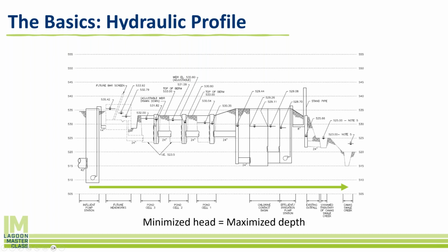Doing this math is extremely important all the way across because A, we need to make sure that if we're trying to move water to the next phase, the water level at that point is lower than the water level here. If this lagoon was higher than this lagoon, water is not going to flow this direction, water is going to flow this direction, and we don't want that.